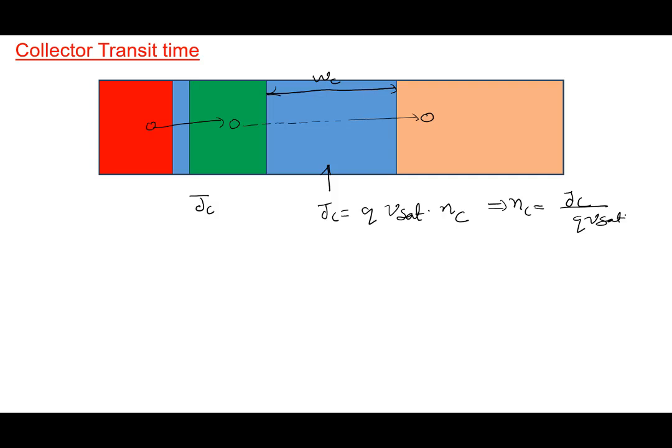Okay, so now imagine, what we are looking at is the collector depletion region. Imagine initially Jc equal to 0. Let's say this is ground. You're reverse biasing the collector, so you're applying a positive voltage here, and let's say you've also applied 0 here for a moment. So you're not injecting anything. Then you can apply an emitter voltage, VE, so you start to inject. By altering this voltage, you can change the collector voltage.